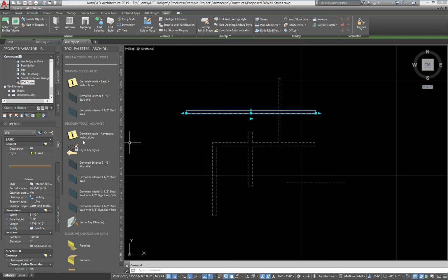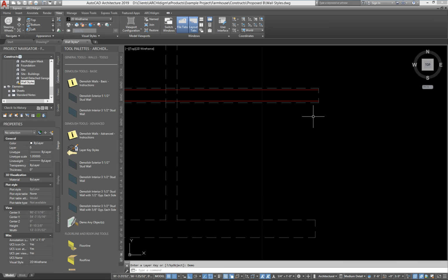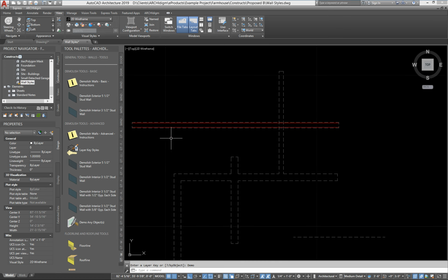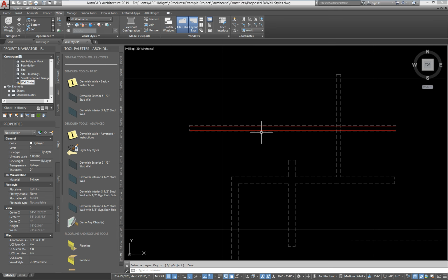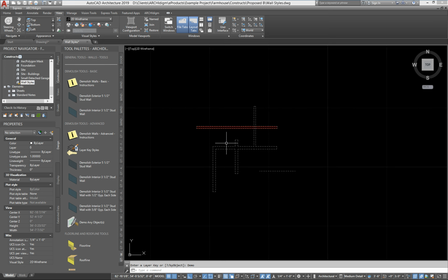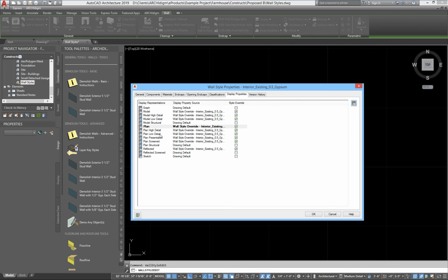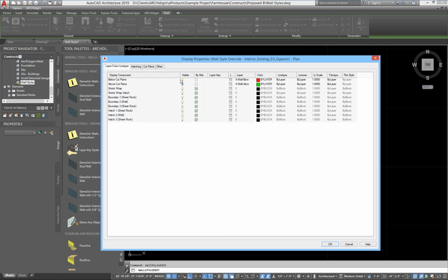So if I go ahead and do this, pick on this wall, it will do it on whatever is set to by layer, but if there's something that needs to have a higher state of settings, like the component inside, it won't do that. So if you do it and you see that it's not quite working on some objects, you would need to go in and take a look internally to see, for example, in plan, what's going on with that object, right? So if there's any overrides.